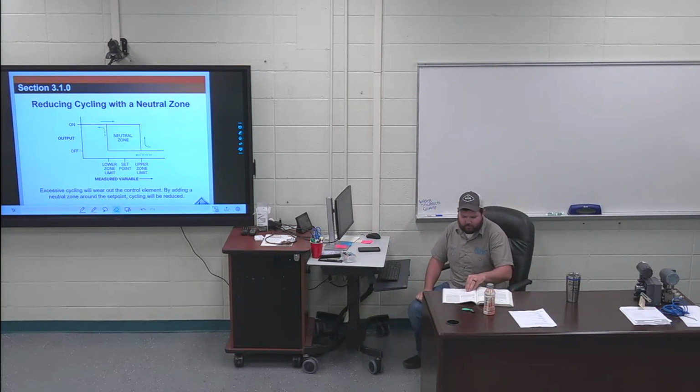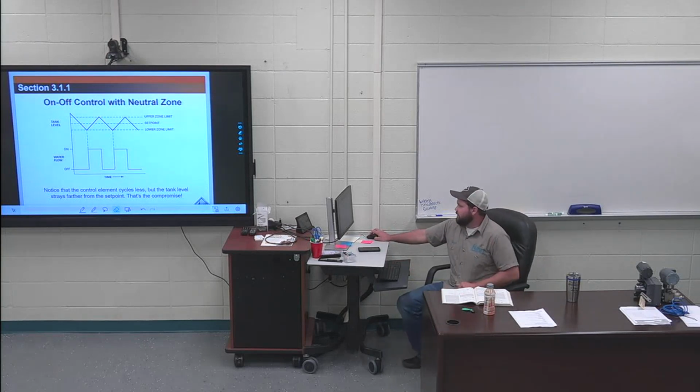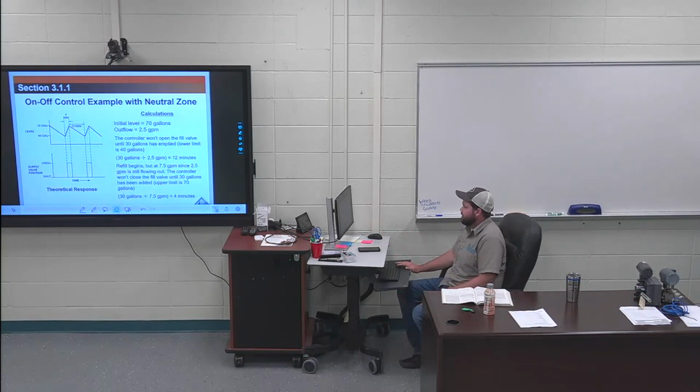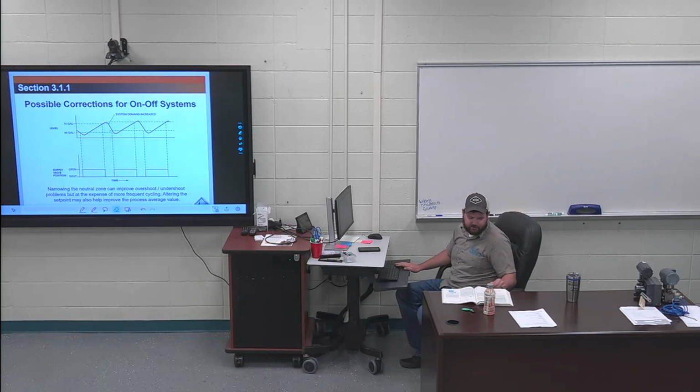Makes sense. Flipping over, they're gonna talk about turning stuff on and off. So this is the actual tank level. And then you can see the water flow being turned on and off. So the tank level's high right here, so my water flow is off. And then you can see my tank level dropping, right? Upper zone. My set point is right here. My lower zone limit, that's what kicks on. So all right here is my neutral zone. Kicks on, stays on all the way till it hits the upper zone, back off, same thing. Same thing as the air conditioning example that I just said, just a different version of that. They go through how fast this stuff can happen. I don't find that necessary, all that's gonna be set up whenever people buy the system. I don't have anything on pages 28 and 29.